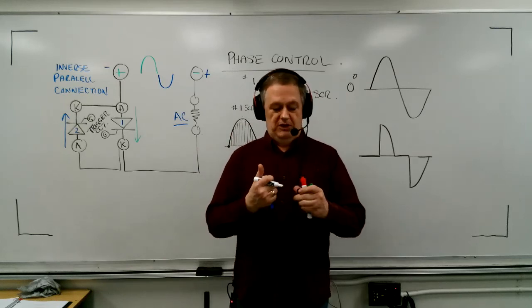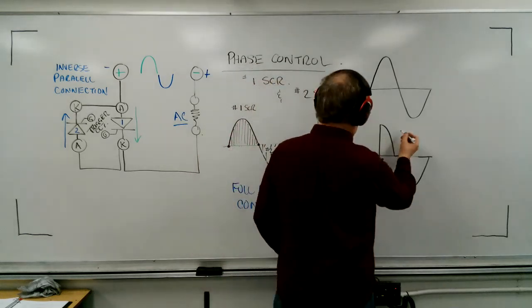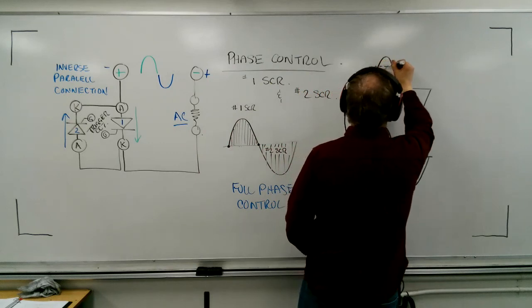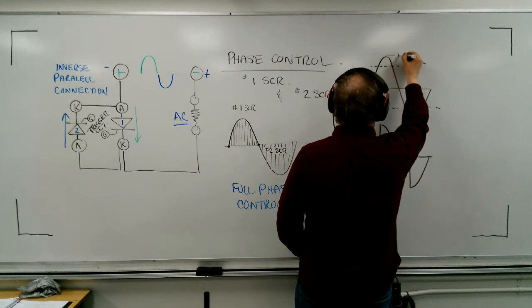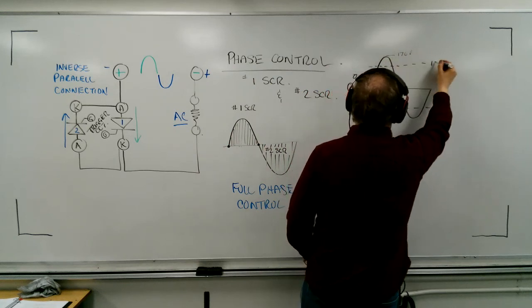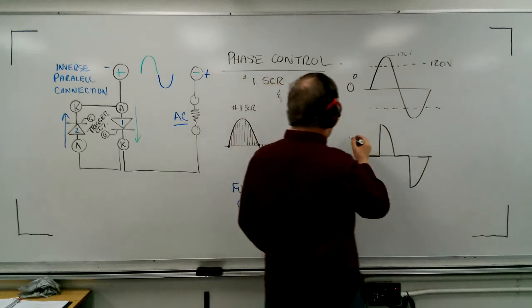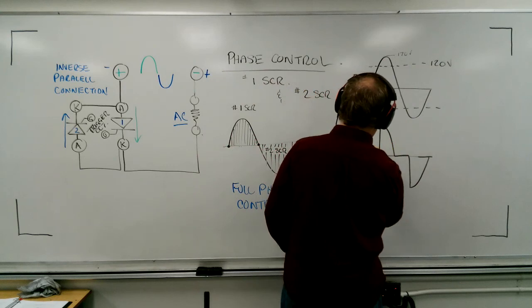0 volts. So what is the value we actually look for? We call it effective voltage. So if the effective voltage of this waveform, if these peaks were 170 volts, we know our effective or line voltage would be 120 volts. This one, if I go to 90 degrees, guess what my effective voltage would be?